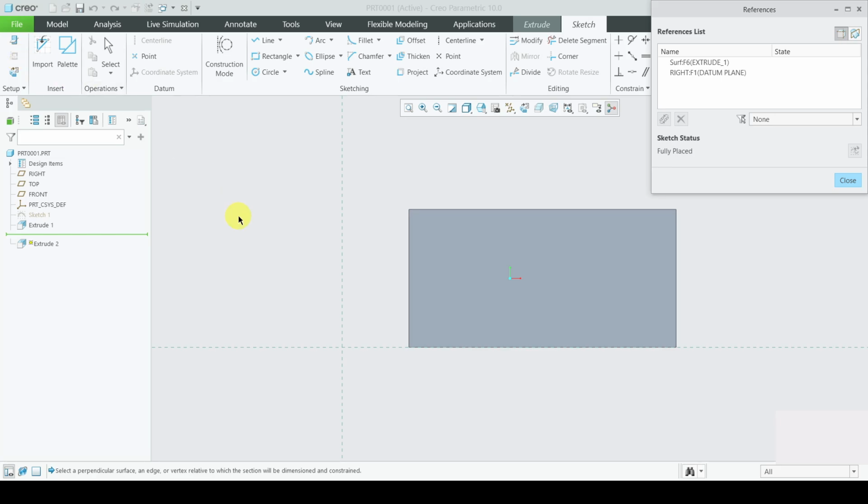In this scenario, how will you use your sketch references? We want a rectangle which is cut in this region from this edge, and we will give a size. So what will be your sketch references? You will select this upper edge and this edge. And you resolve the reference to sketches is applied.